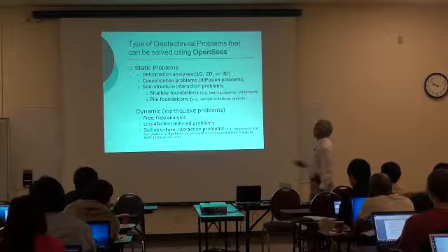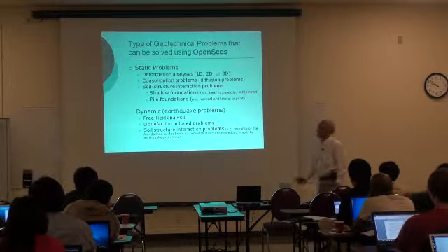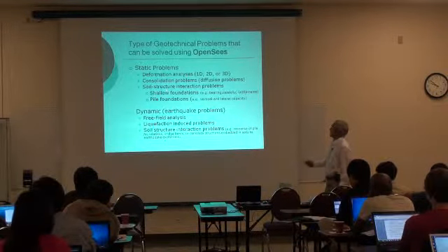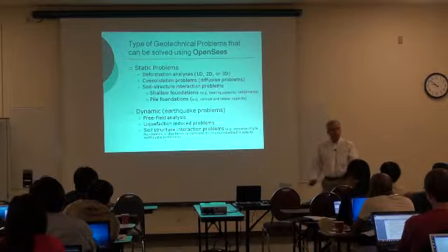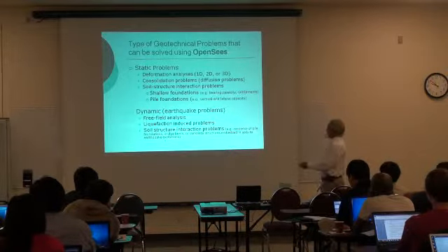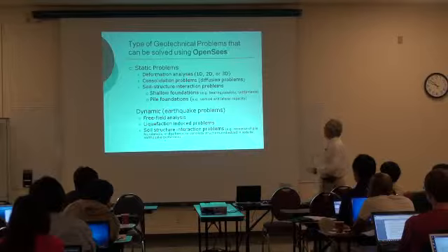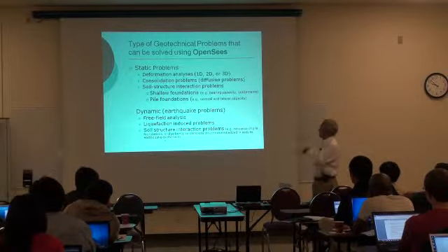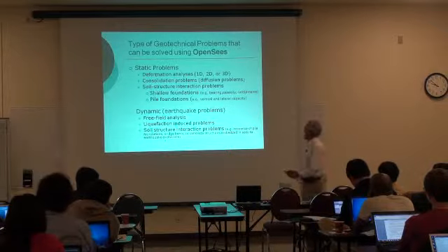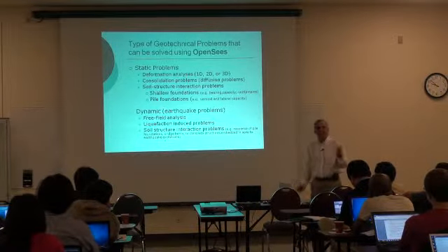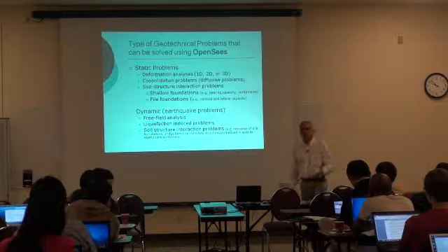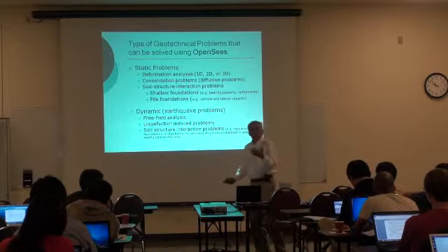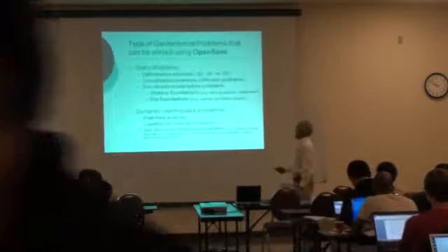We would like to consider soil structure interaction problems, in particular shallow foundations, with bearing capacity and settlement problems coming to mind, and also pile foundations. We would like to look at vertical and lateral capacity. When we go into the dynamic or earthquake problems, we look at free field analysis, a typical thing that we do in geotechnical engineering, and we would like to do that with a tool like OpenSees.